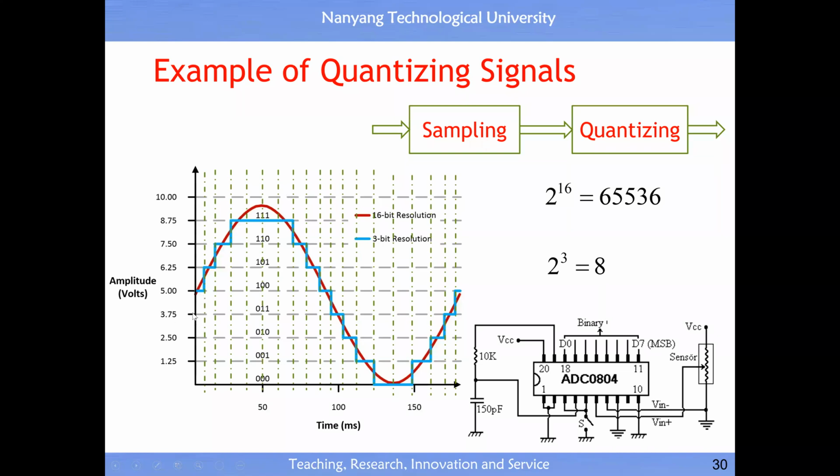Then I do a third prediction, 011. Again, I do a DA conversion to get this analog value and do a comparison. You see, a big gap. Then I do another prediction, 100. I do the DA conversion to get the analog value. The predicted value and the real value are very close, so done already, all right?